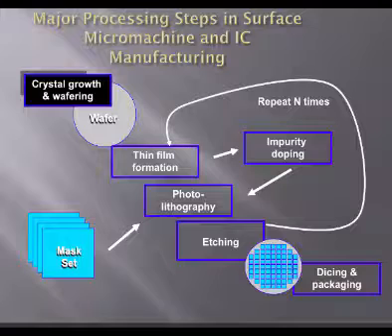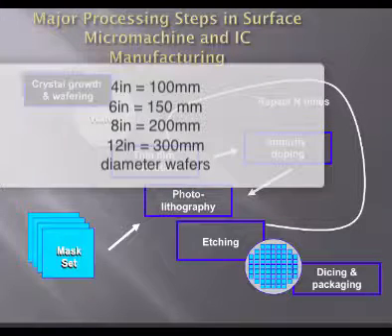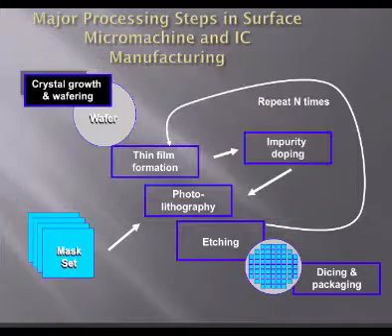Most MEMS companies produce things on 6-inch wafers instead of 8-inch. Most semiconductors are doing 8-inch, and then the really big ones, like the Intels and the AMDs and the global foundries, are doing 12-inch wafers. But that's real high volume. Then you can justify the equipment cost. But if you have a medium or low volume, you're going to do 6- and 8-inch wafers.